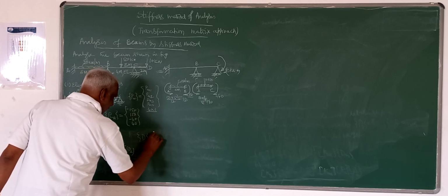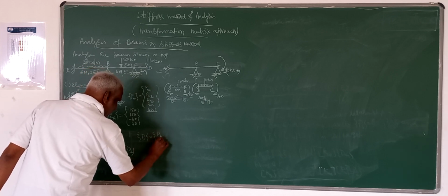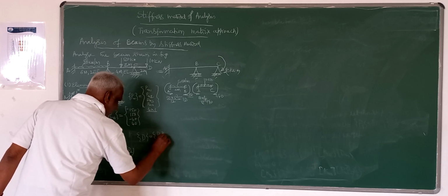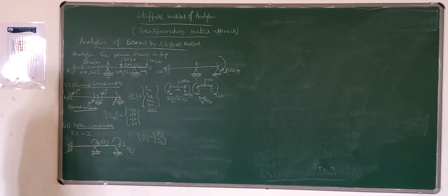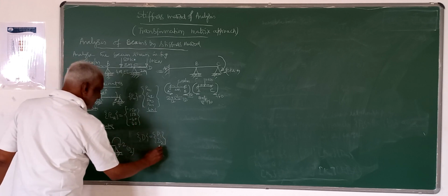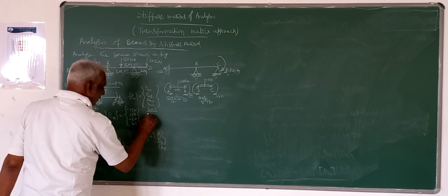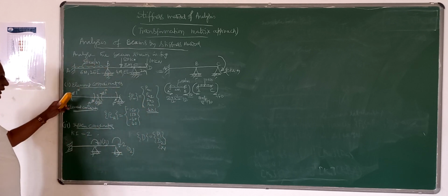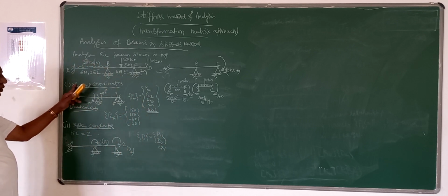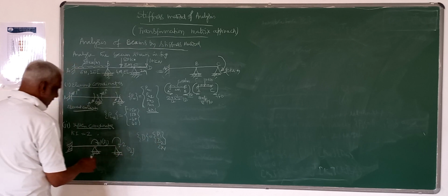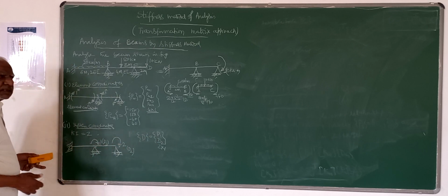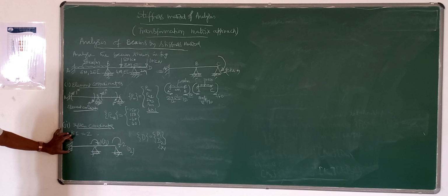So here I have to evaluate these 2 displacements corresponding to these system coordinates D1 and D2. So during analysis, now I have to determine the unknown internal member forces corresponding to element coordinates and unknown displacements corresponding to these 2 coordinates, because here there cannot be any displacement.